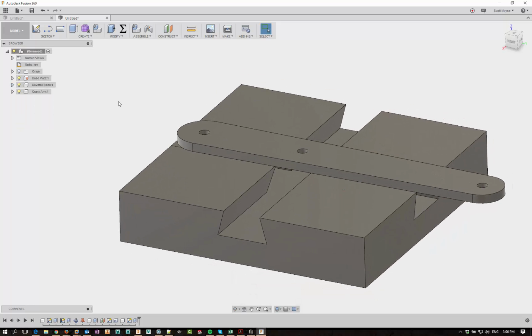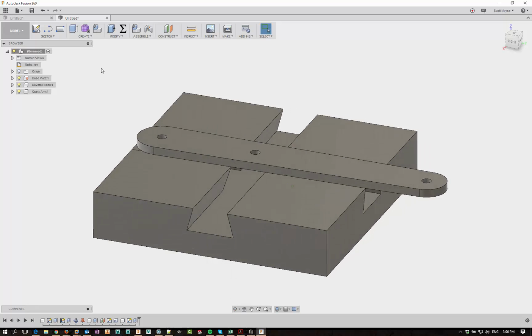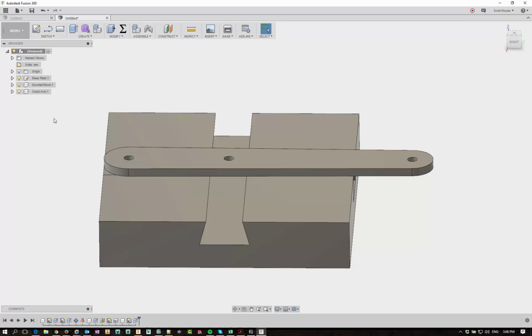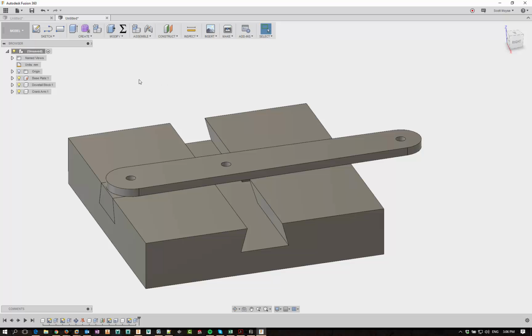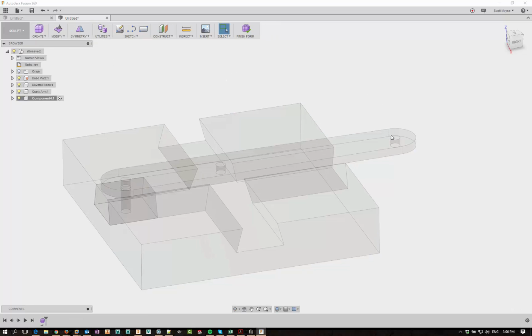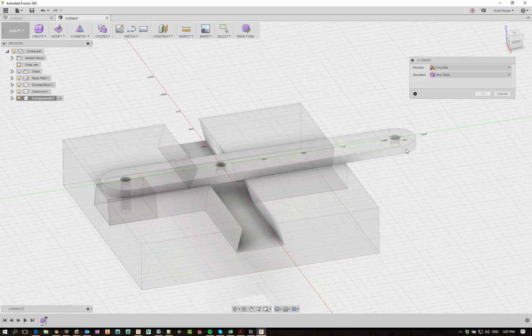And now let's just, for the hell of it, make a handle. Your technique with revolving and that followed on from your previous videos nicely, so that was cool. I'm just gonna do a T-spline one though, so create form, cylinder. I'm gonna pick this face to drive it off, and that mid center point.